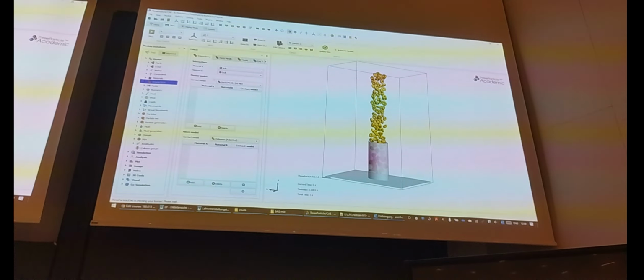So, let's go to interactions. Here, we need interaction between bulk and steel, and between bulk and bulk, of course. We need between bulk and plexi. That's it, right? That's it. Everything else is cool so far. Bulk and steel is the first contact to the floor. Restitution of 0. Donuts are quite soft, right? 0.1. Static friction higher, let's say 0.5, 0.4. Bulk, I would say, ooh, this is even more soft, 0.01.